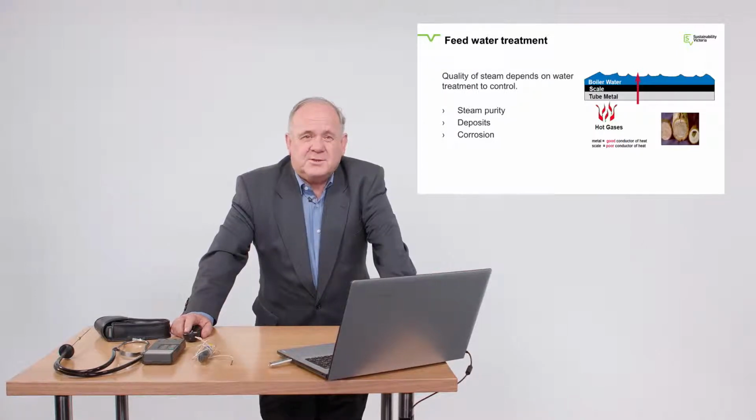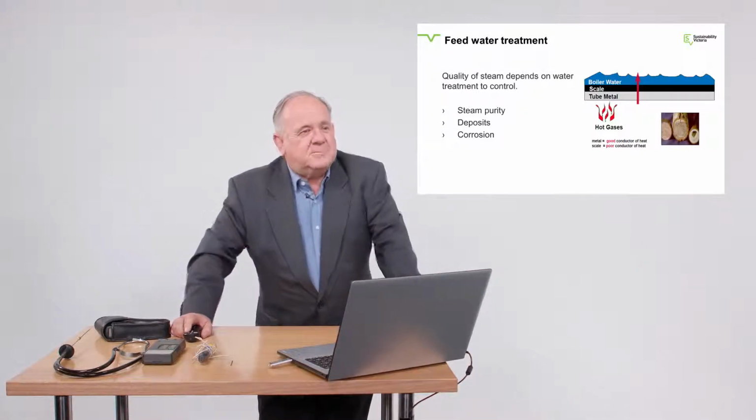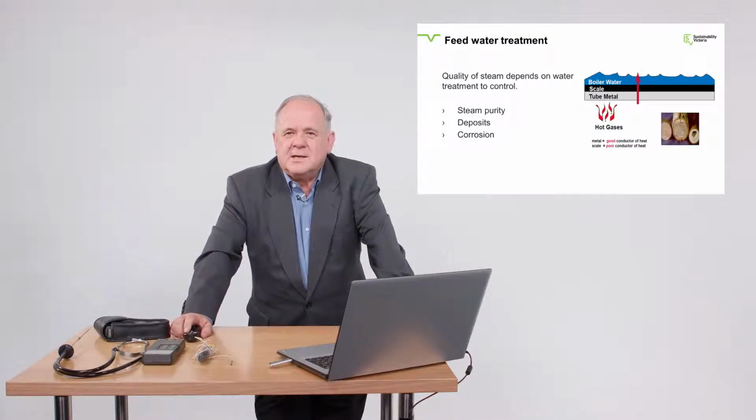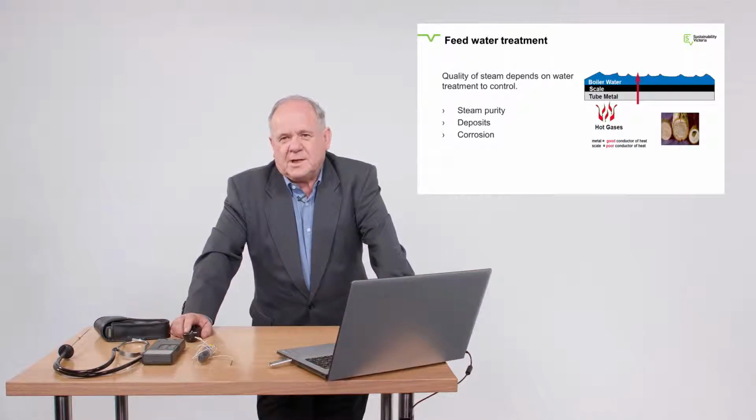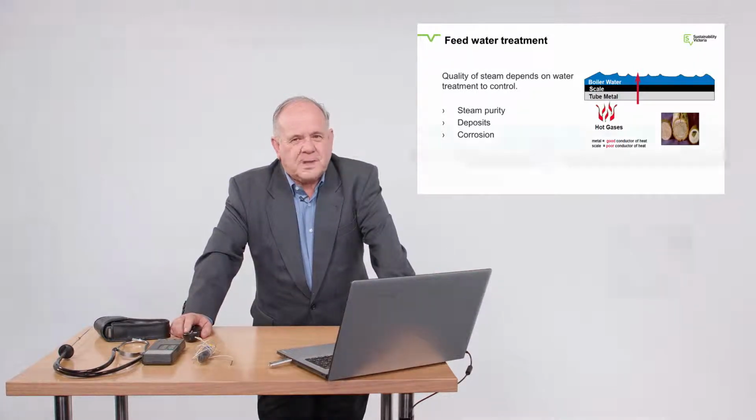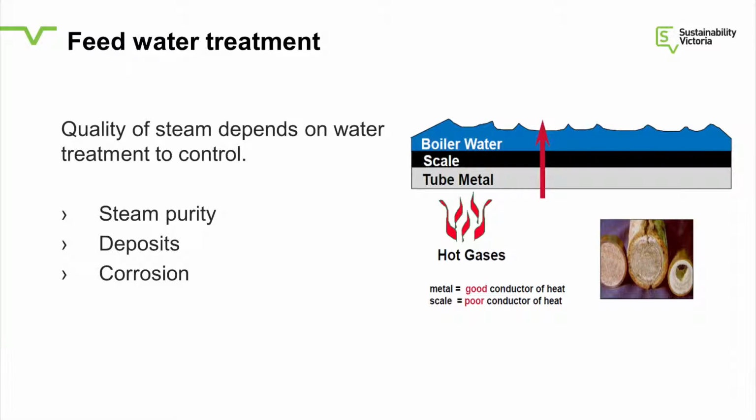I've seen boilers that are 30, 40 years old, package boilers that have been well treated. But again, it's because of the focus on treatment of the water and keeping the tubes nice and clean. If you look at those tubes there, you can see they're supposed to be open tubes in that photo. That's an example of a boiler that hasn't been treated very well. So obviously if you clog the boiler to that extent, water can't flow through those tubes. So obviously it'll bypass and it'll become very inefficient.